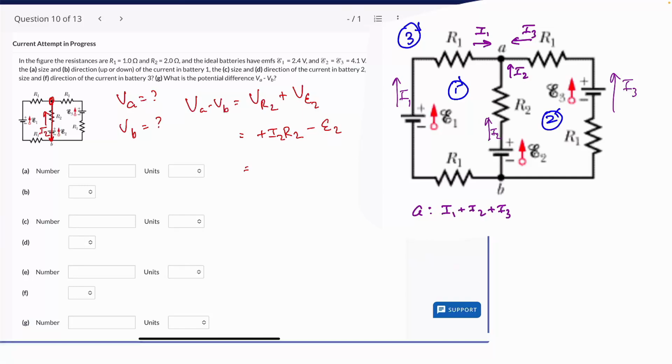All 3 of them, right? And what's going out? None of them. What do I know? One of these has to be negative, right? I can't have 3 currents all going into a junction and nothing coming out. So it means that I have picked wrong for one of the directions of my currents here. So do I go back and restart the whole problem? No. The math will work out. It's just I'll get a negative current.